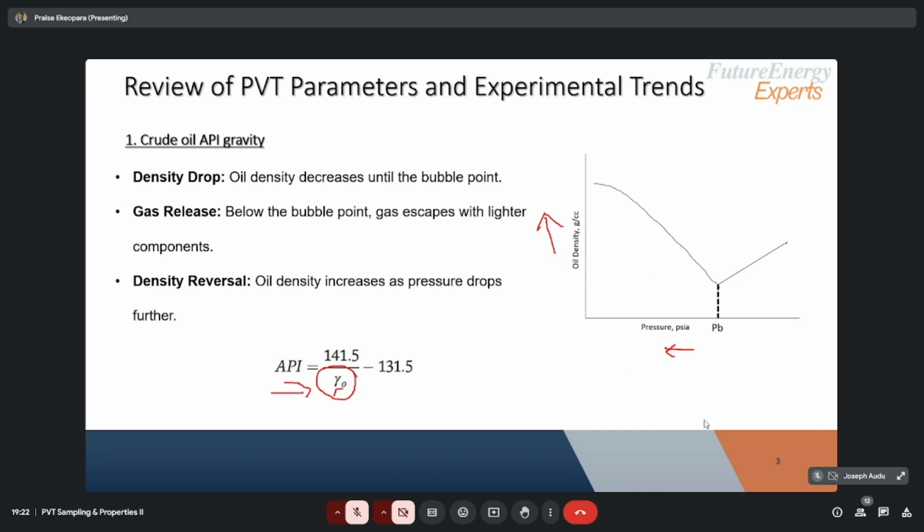Okay, so this first instance, whether I indicate it in any of the plots or not, usually describes our initial pressure, which we can refer to as our reservoir pressure. So for density, how does it work? At reservoir condition, it is more dense, like above the bubble pressure. You know, this is the bubble point, like the saturation point. This is the reservoir pressure.